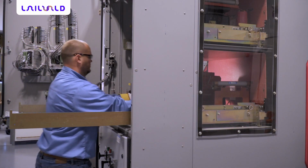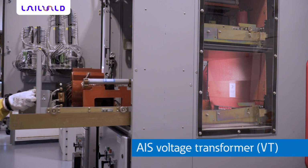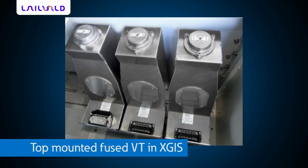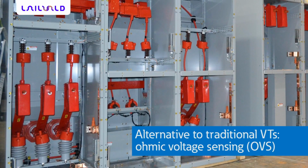Voltage transformers, VTs, for metal-clad AIS must be mounted in withdrawable drawers to maintain construction standards. VTs for metal-enclosed GIS switchgear are fixed-mounted but can be removed or serviced as needed. Alternatives exist for traditional VTs. Resistive voltage dividers, which are not susceptible to transients or ferroresonance, can be used for sending 120-volt AC signals to relays or meters in your assembly to perform your essential protection and controls functions.